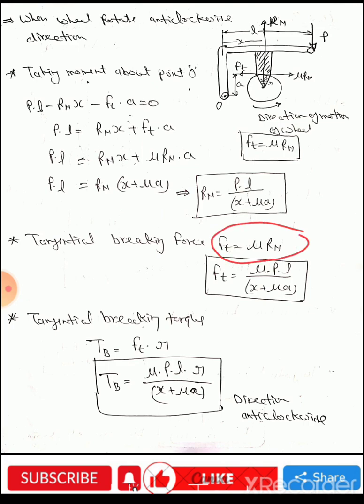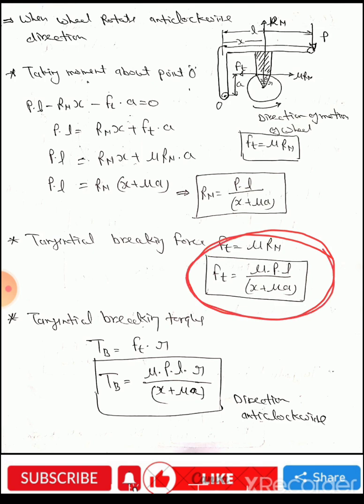Putting the value of Rn from here into the tangential braking force equation here, we obtain the tangential braking force Ft equal to mu PL upon x plus mu A.